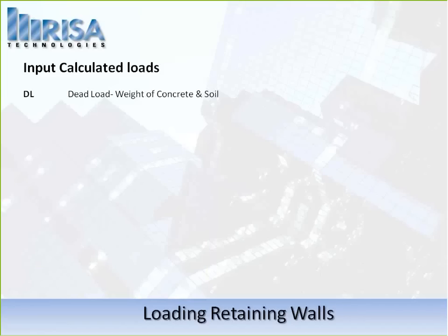So what we see here is dead load is going to be categorized for the weight of our concrete and our soil. We've got live load, which is going to be our surcharge above the retaining wall there. We also have hydrostatic loads. Any lateral pressure or hydrostatic loads are going to go right into the hydrostatic load category. That might be a new one for you. We've created a new load combination set so that the generic load combinations, the defaults that come out, you'll see I've also now included this HL for hydrostatic load. So we're always including that.